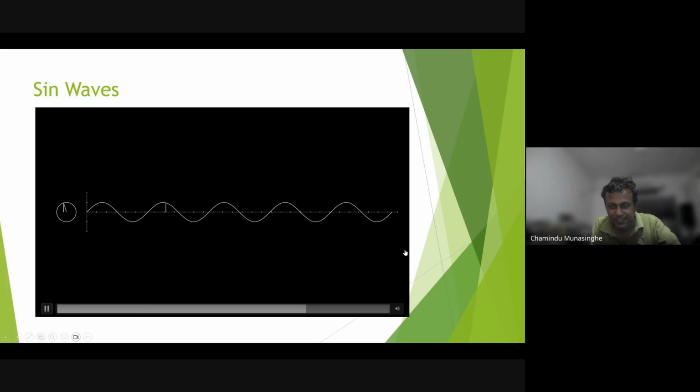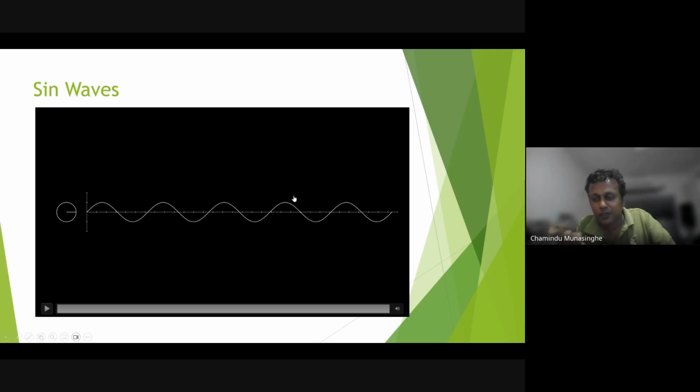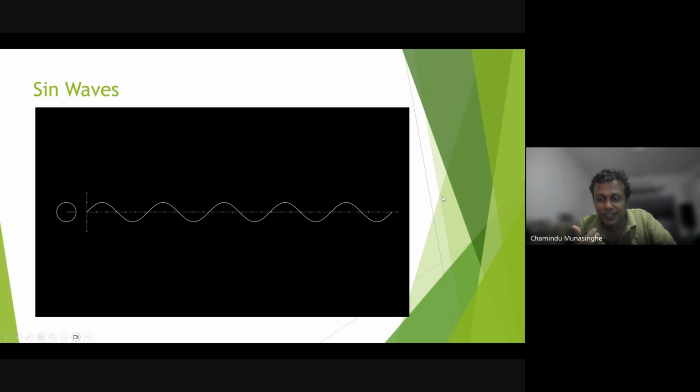When we deal with GNU Radio and complex waveforms, this idea of negative frequency comes up. It's nothing but the same vector rotating the other way around. If you only take the projection on one axis, we can't distinguish between positive and negative frequencies. But if you represent it in quadrature form, you can distinguish between positive and negative. That's just something that came into my mind. I just wanted to tell you guys while we are looking at this.